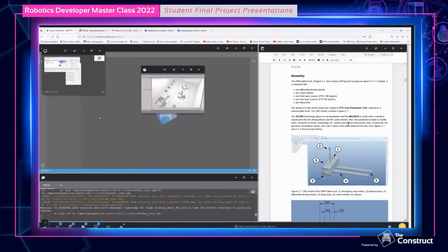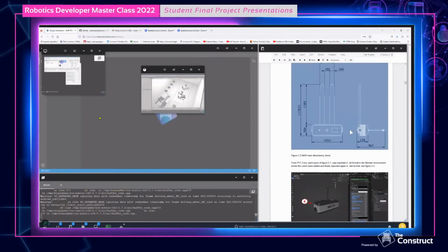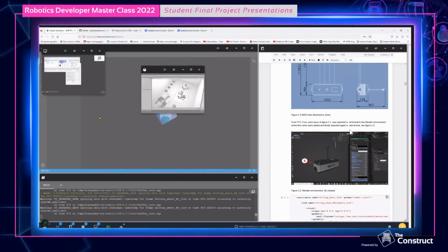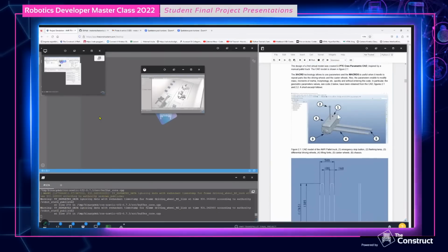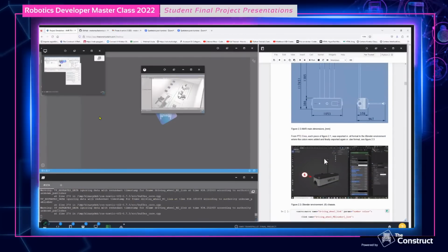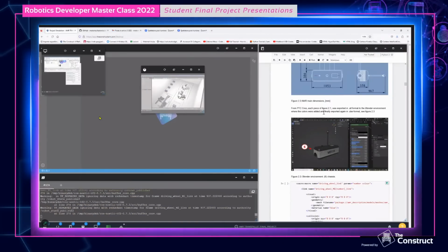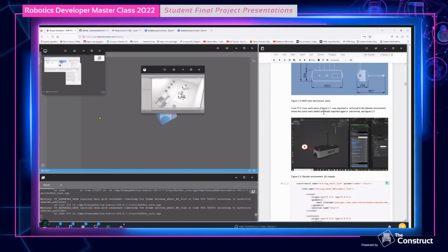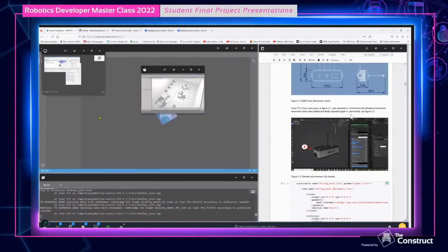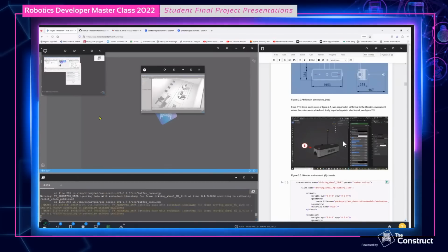There is an initial part of the program in which I list all the parameters, and I interact only with this. The CAD I created in PTC Creo. I used Blender to add the colors. In particular, it's important to export the file from Creo in STL format, import it in Blender, and export it in Collada, DAE, which keeps the colors.